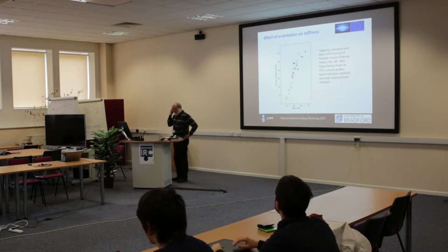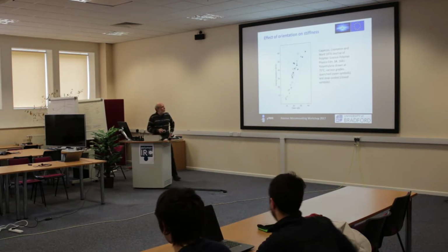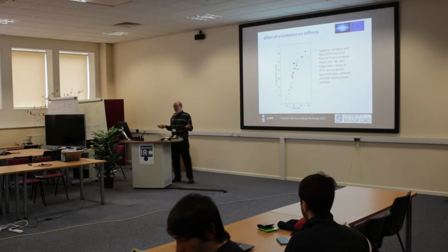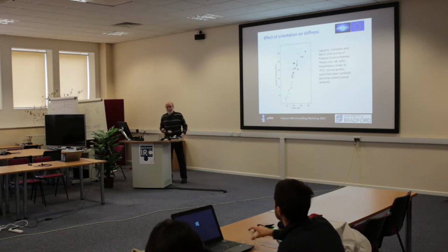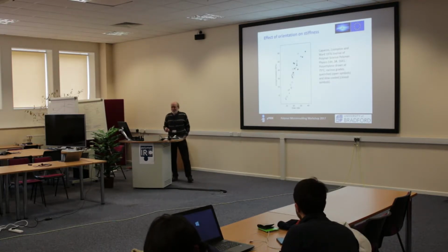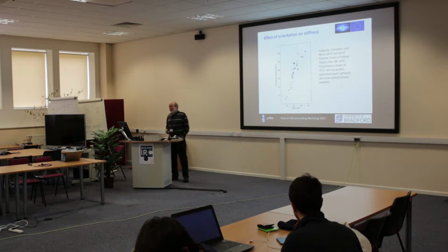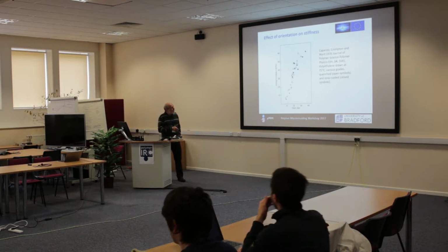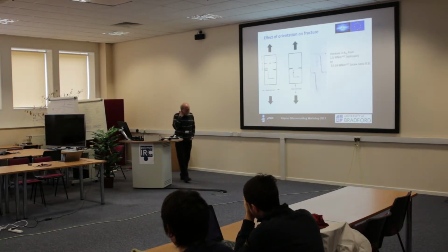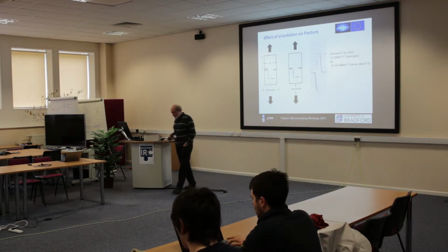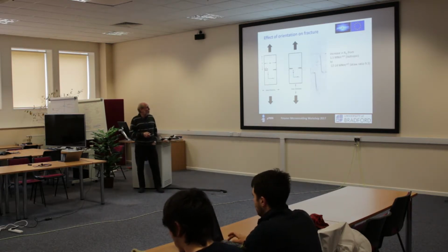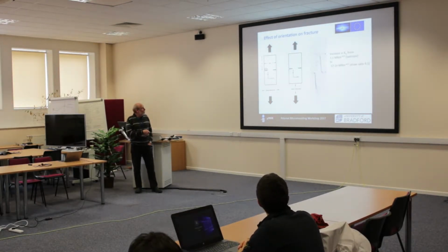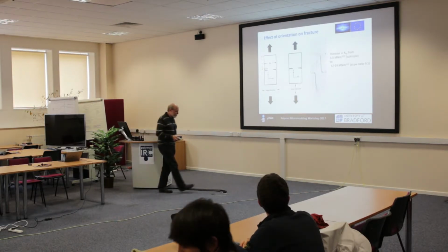You can draw fibers up to about 100. So you can actually take the modulus up to maybe 100 gigapascals, which is compared with steel, which is 200. That's quite significant. Okay, and also you don't just affect the stiffness, you also affect other things, various physical properties such as thermal conductivity and so on. And mechanically, you affect the fracture behavior, because